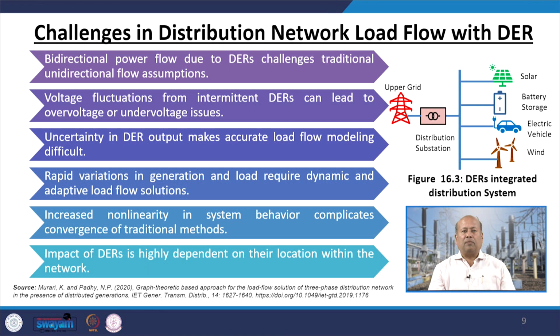Now, in case of distribution load flow with DRs, there are many challenges, because what we have discussed so far is a simple distribution load flow algorithm having loads and generation at the substation. However, the moment we integrate distributed energy resources, bidirectional power flow due to DR challenges the traditional unidirectional flow assumptions.